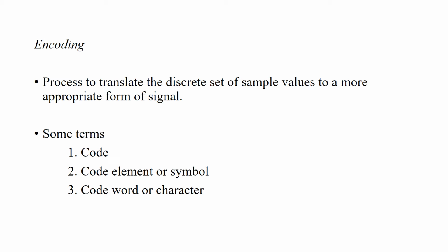And we can say binary code has two symbols, 0 or 1. And ternary code has 3 symbols. The maximum advantage over the effects of noise in a transmission medium is obtained by using binary code, as a binary symbol can withstand a relatively high level of noise and it is easy to regenerate it. Now let's go to the next one.